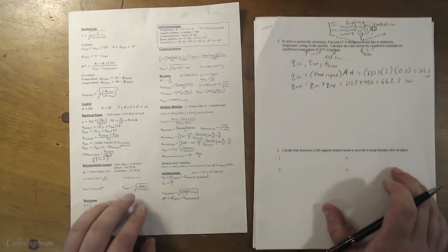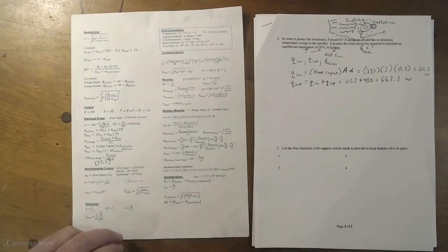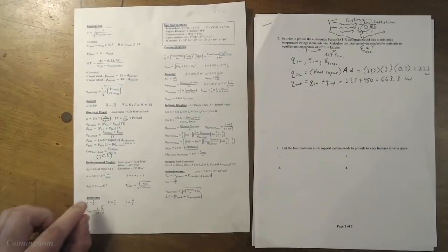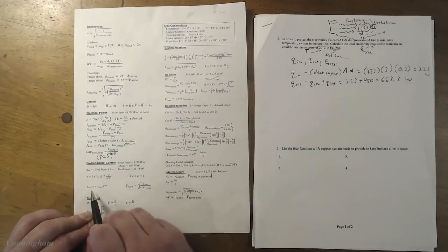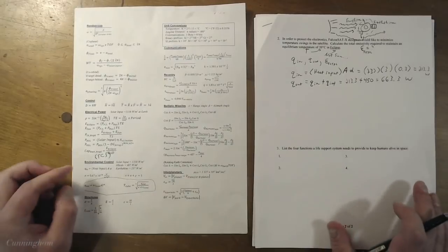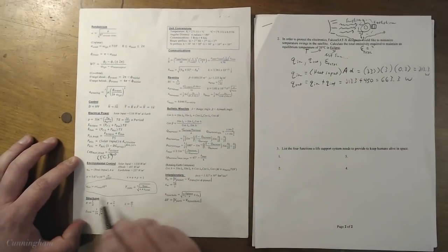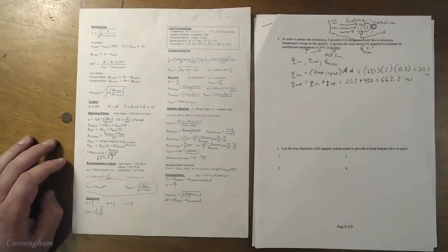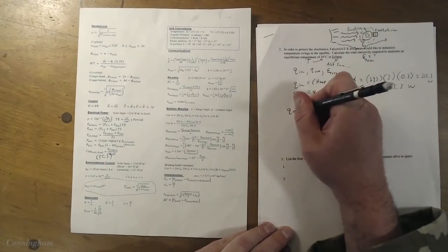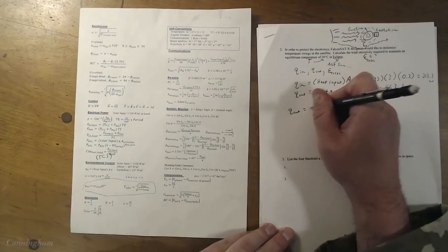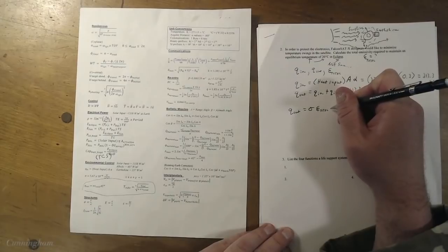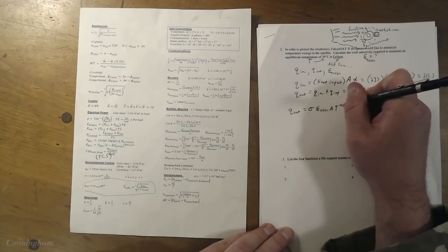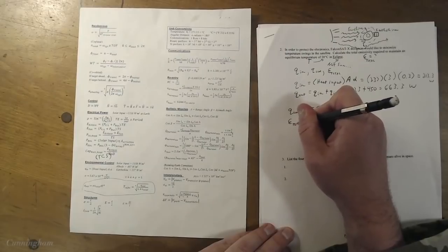Now, this is a little different. Remember how last time we used this T cube equation to find the temperature of our cube? Well, we can rearrange either this equation or this equation. These two are kind of brothers. They're just rearranged for you, so you don't have to go through the mental gymnastics on a GRE. They're two sides of the same coin, the exact same equation rearranged. So it's easier for me to just take the Q out equation and isolate total emissivity from that.